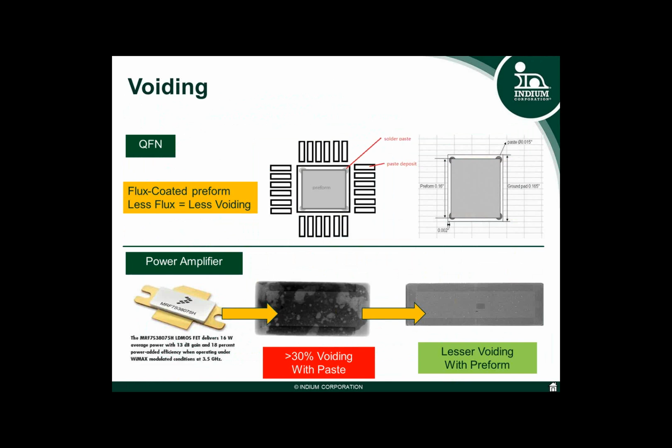Moving forward to the QFN examples that Bob showed, again with fantastic videos, thank you Bob. But here is a little bit of the benefits of the design features, because not all manufacturers out in the market are giving the design guidance as to which preform is desired underneath. But I would echo what Bob was saying. I would review the component TDS to find out the thermal demand and to find out if your PCB has been designed with a traditional land pattern or one that's been designed for the component.